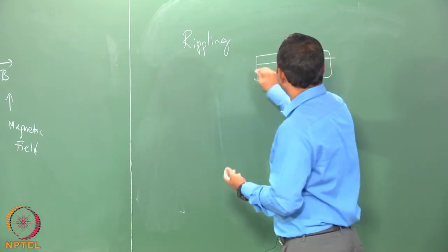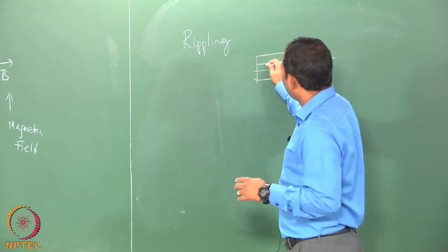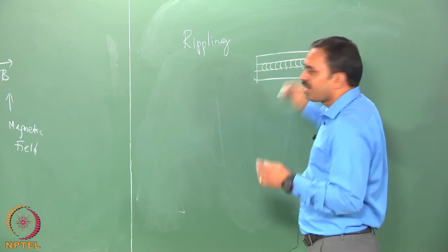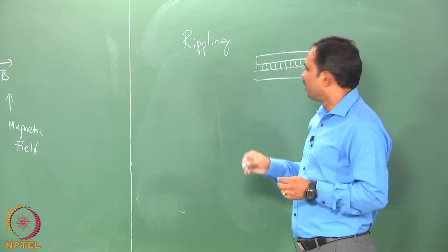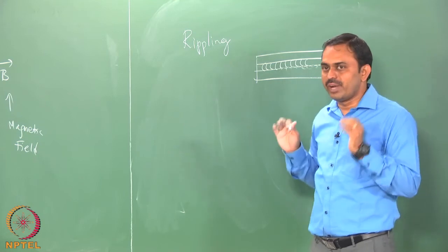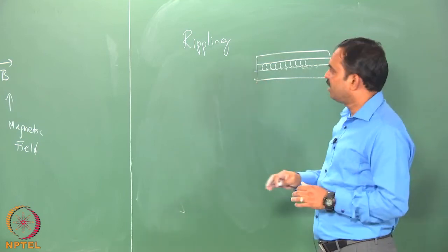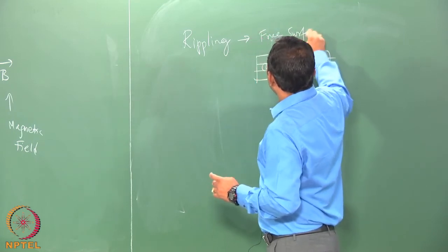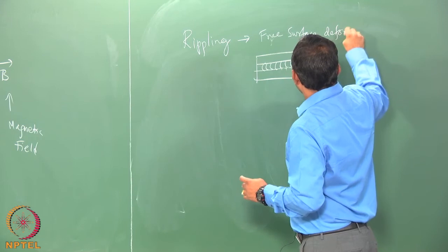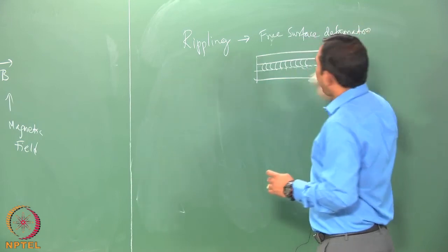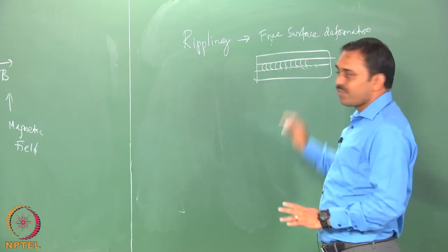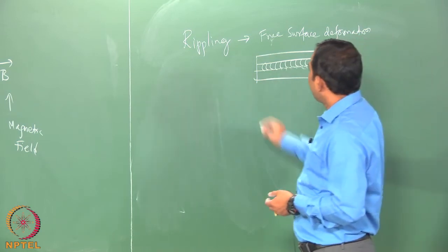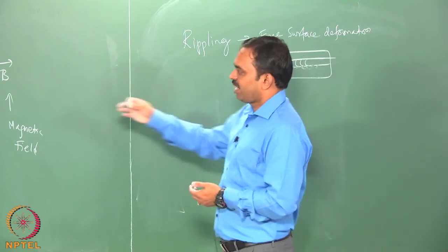Okay. Normally a good weld, what is called good weld appeal, is going to look like that, and each of these is basically an arc shaped surface undulation which is supposed to be very uniformly spaced for a good weld. This surface rippling is basically due to the free surface deformation. And that is not considered till now, and there are ways to model it. We will come to it if there is sufficient interest among the participants. And there are other things that we have not considered, for example,